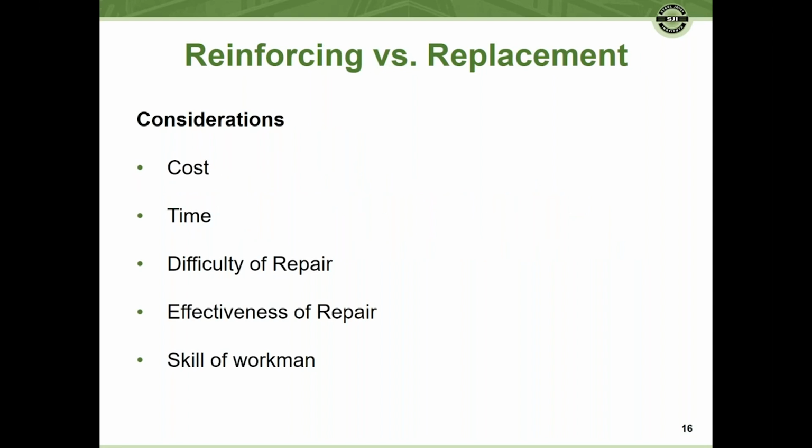Some things to keep in mind with regard to reinforcing and placement. Things we need to consider are the cost, the time, perhaps the difficulty of the repair, and even the effectiveness of the repair, and then of course the skill of the workman. All of those things need to be considered when we're thinking about replacing the joist versus reinforcing the joist.